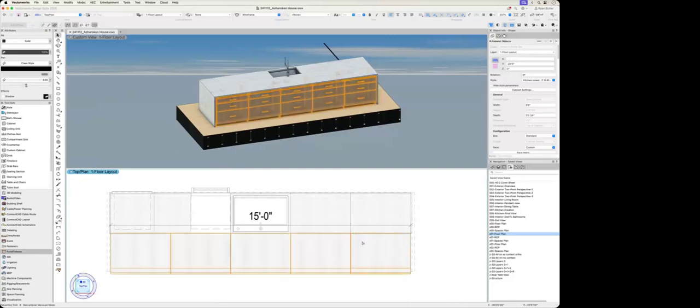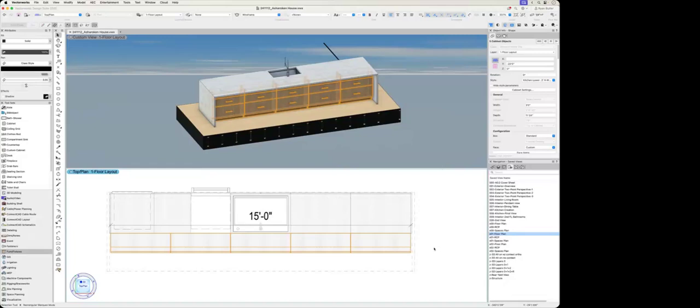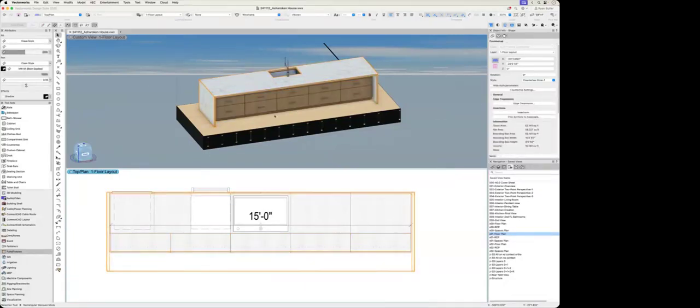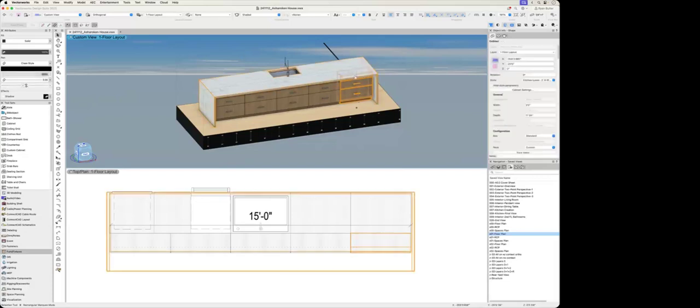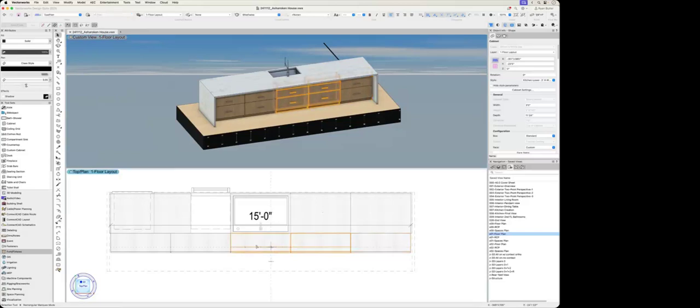Okay, cool. Now the depth is not what I want either, so let's have those all selected, and we'll change the depth to 11¼ inches. And that's the nice depth that we want. Okay, so now if you look, these are all drawers. There are three drawers. You can see that the third one's tucked in there. But if I don't want the drawer layout like that, I can change that if I want to. So let's keep drawers on either side, and then we'll take the middle 3 and change them to doors.